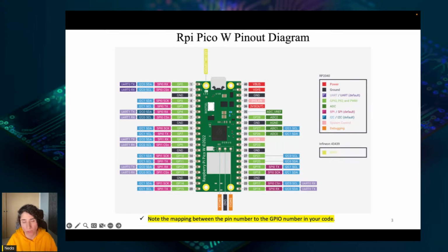ADC works by taking samples of the analog signal at regular intervals and then quantizing and encoding each sample into a digital value using a mathematical algorithm. The output of an ADC is a binary number that represents the original analog signal in a digital form, which can then be manipulated, stored, or transmitted using digital electronics.